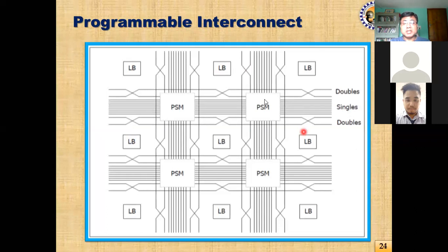You can see that there is a matrix. This is called a programmable switch matrix, PSM. This type of PSM was there in CPLD also, as the programmable interconnect. The name was given over there, but they have a very similar function. The single lines are actually wires. You can think of them as buses which carry the signal. They are coming from, suppose, the output of this.